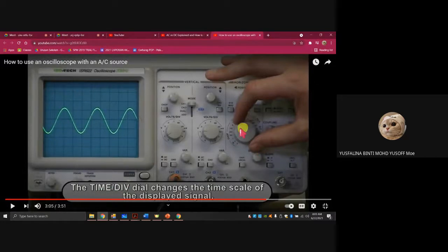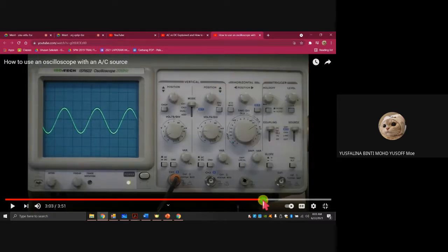For this one you can also change the time. So what is one division here equal to? You can change here. This is the time here, you can change the time. How much is one division equal to for the x-axis? Just now we changed the value for the x-axis, right? So one division here equals what? You can see ms, right? You can see here the symbol ms.